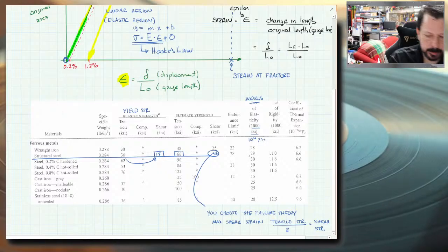And then for this particular material, 29 million PSI would be the modulus of elasticity. We have this one, same thing, but this is rigidity. We'll do that at the end of the quarter. Modulus of elasticity talks about stretching somehow, an axial stretch or maybe a flexural stretch, and rigidity is twisting. So we don't need it just yet.